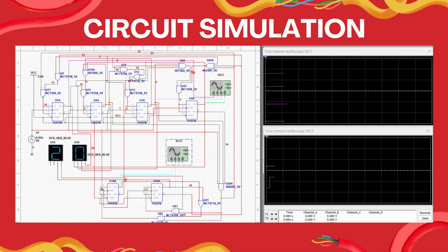Once the logic was finalized, we built the circuit using Multisim software. We connected all JK flip-flops and logic gates as per our derived expressions. The simulation demonstrated that the counter correctly counts down from 20 to 0 and then loops back.